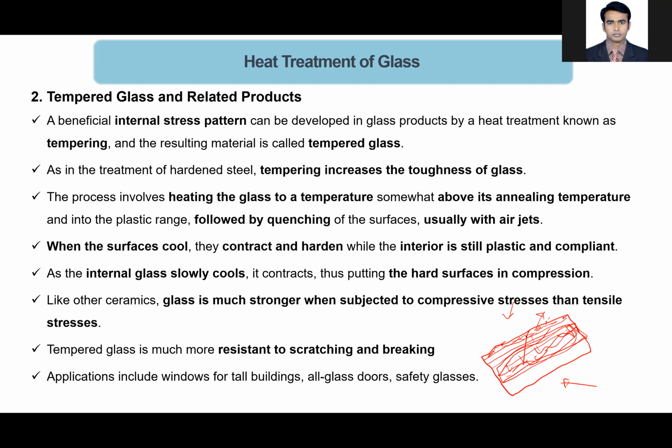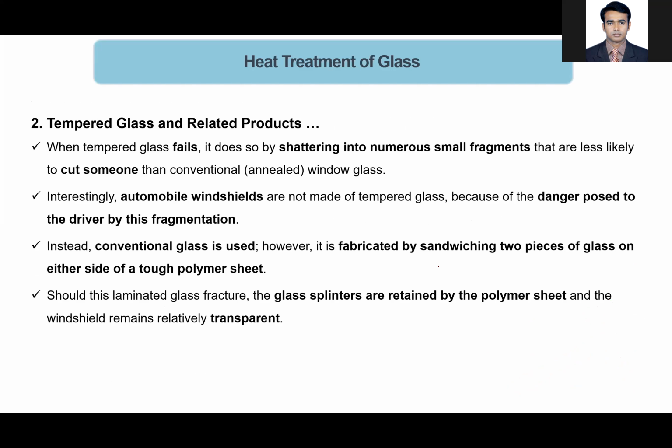It's a gradient. If you plot the hardness of the material, the hardness at the surface will be higher, then at the core it will be minimum, and then on the other surface it will be higher again. And if you plot the toughness, it will be something like this: the toughness on the surface will be less, and in the inner core the toughness will be high. It's a gradient, not a single layer. Did you understand? Yes, sir.